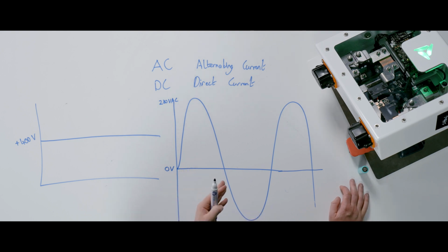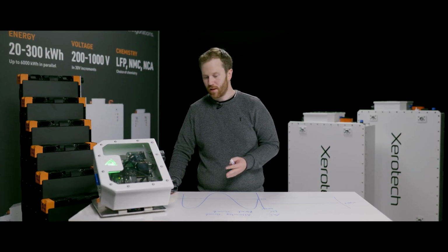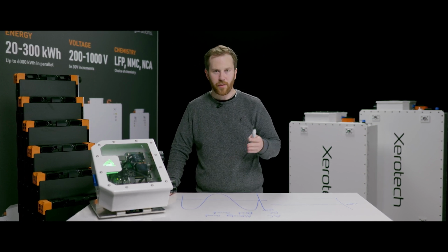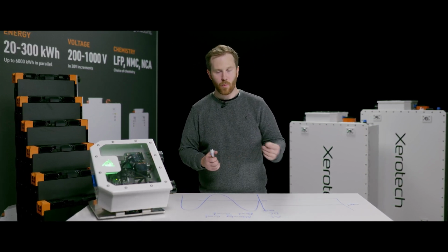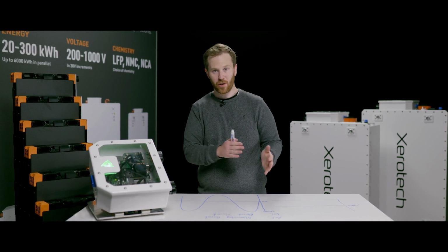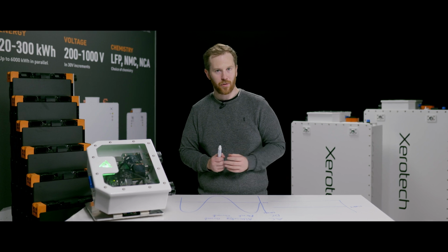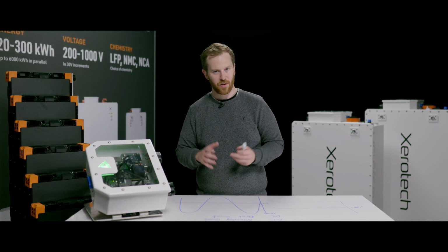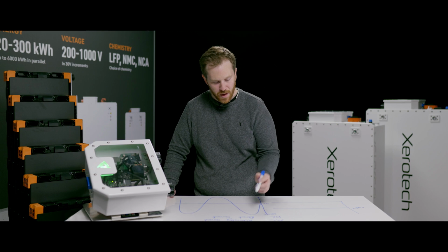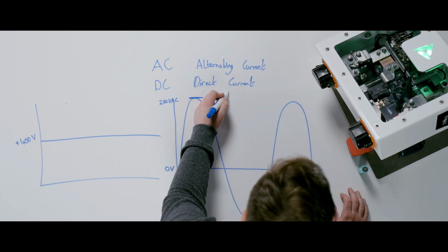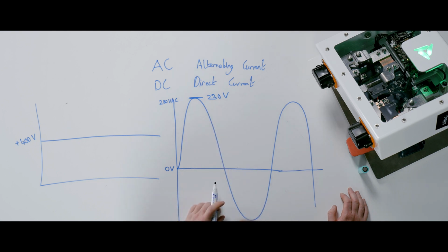One of the most important things to understand about batteries, about voltage, about AC and DC is voltage is a potential difference with respect to somewhere else. It's a potential difference. That's incredibly important, and it's probably the single most important lesson you'll get out of today in terms of handling a battery. If we say a voltage up here is 230 volts, that's with respect to something.